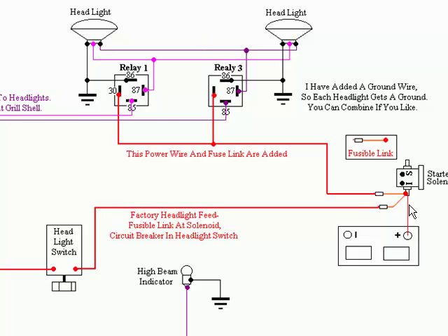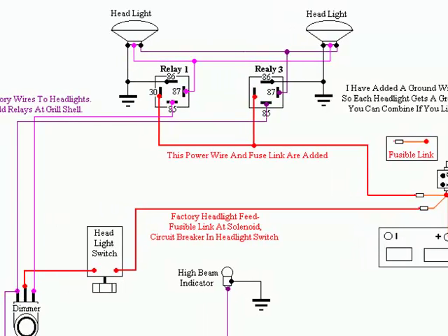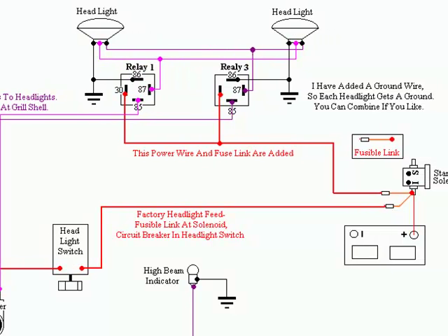Anyway, I checked out circuits on the internet to come up with an example, and here is one. And here's the positive, that's from the battery, and that's indicated by a red wire. Notice there's nothing on the negative, but that's because it's connected to ground, just as all the other appliances here, such as the headlights or the high beam indicator or the dimmer over here. In the schematic the negative actually should be connected to ground as well.